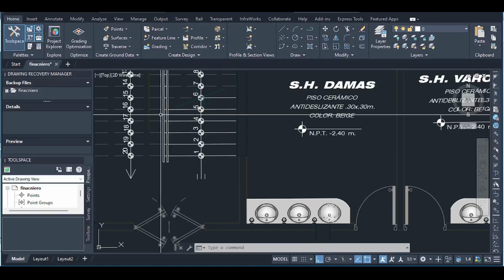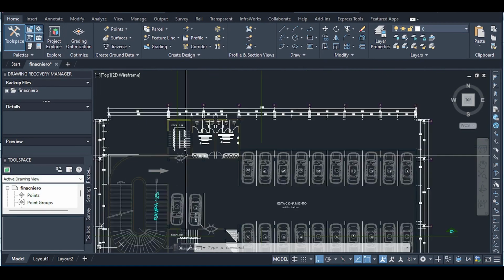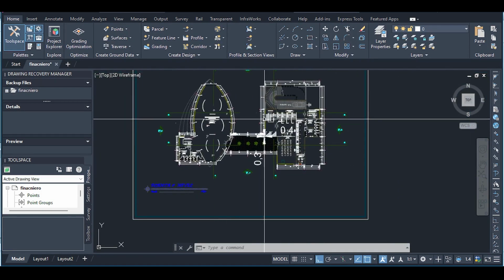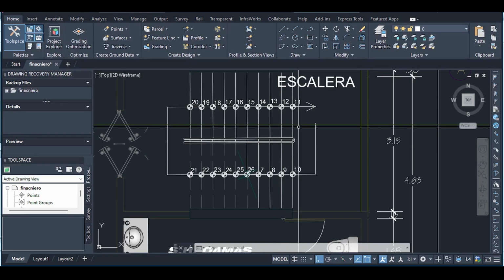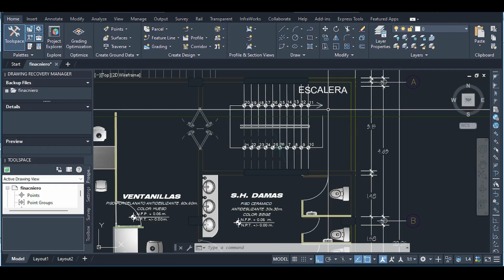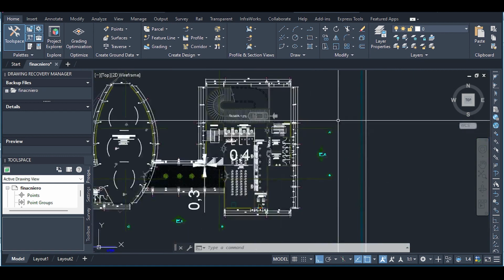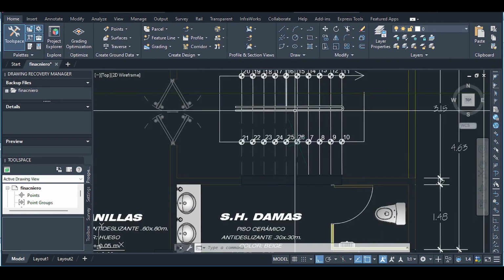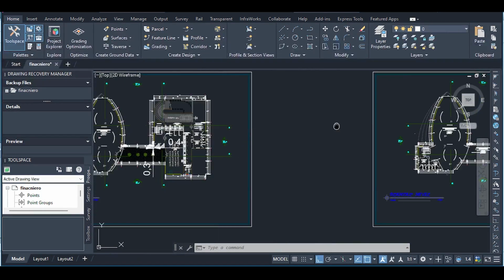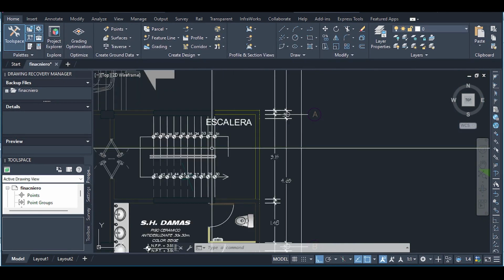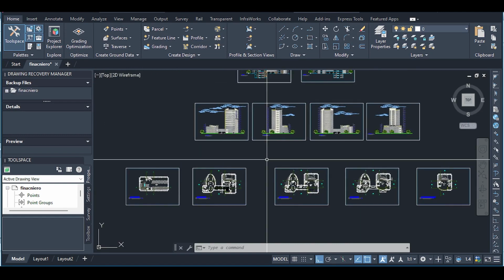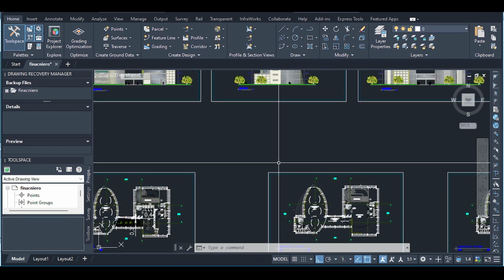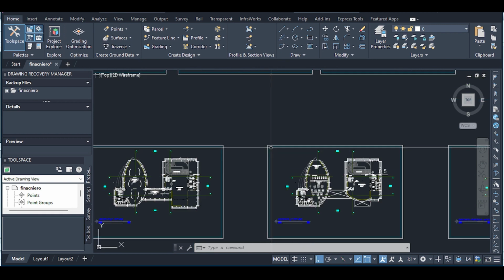I am surprised that the architect did not change the number of stairs, although the story height changed. I'm not an architect, but it doesn't sound right. If I go up, on some floors each step is, I don't know, 17 centimeters or something, and on other floors each step is 20 centimeters. This will cause accidents because humans are used to having the same height of stair in the staircase. You cannot just change the stair height between stories.